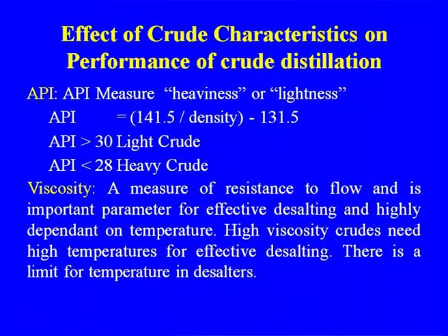Similarly, viscosity, a measure of the resistance to flow, is an important parameter for effective desalting. As I told you, low or high viscosity will have an important role in the desalting or the separation of the salts. High viscosity crude needs high temperature for effective desalting.